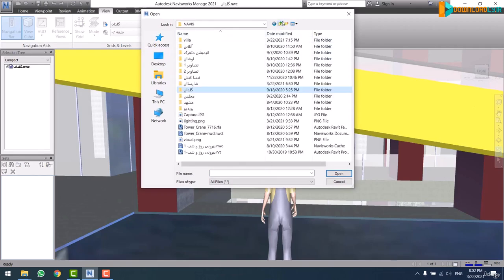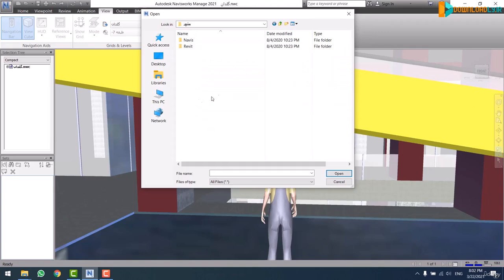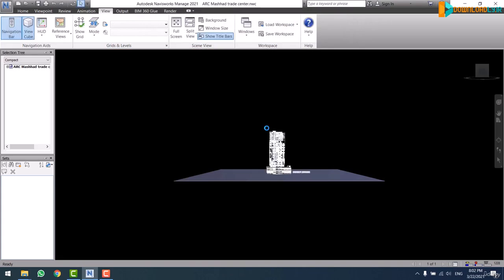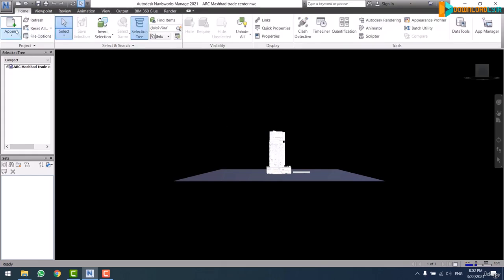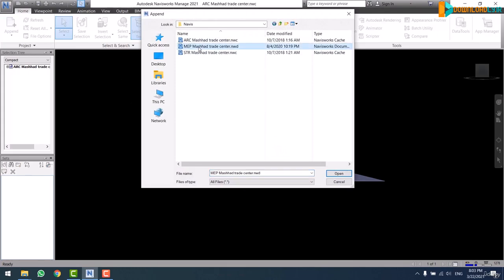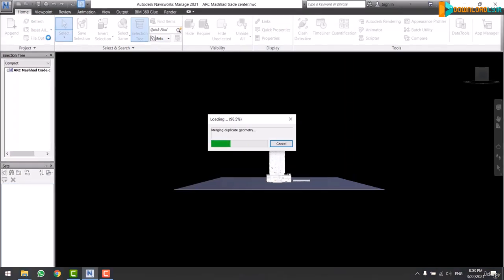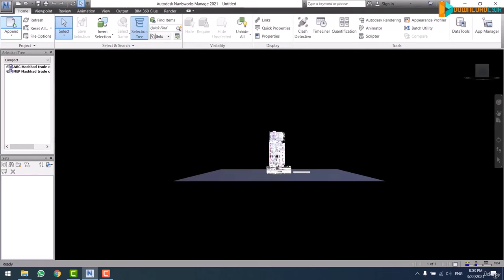Next, I'm going to show you another functional item. While navigating in the scene, let me open one of my projects. Wait for a second, please. As you know, we can present installation, architectural and structural projects, among other things, by using Walk. For example, I'm appending the installation project this way. And after that, I append the structural file.